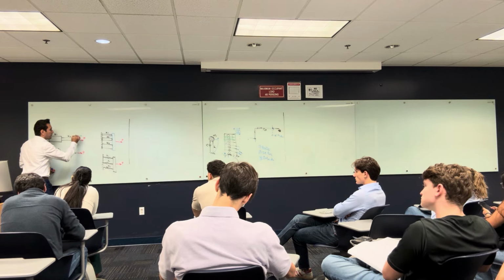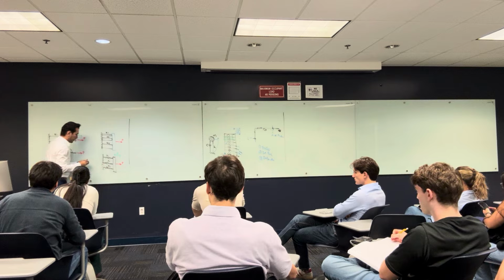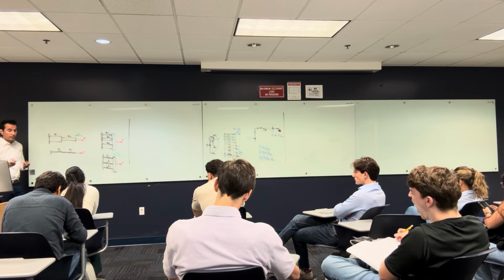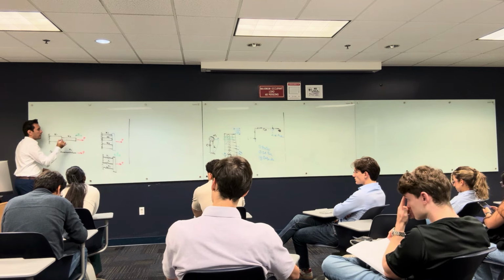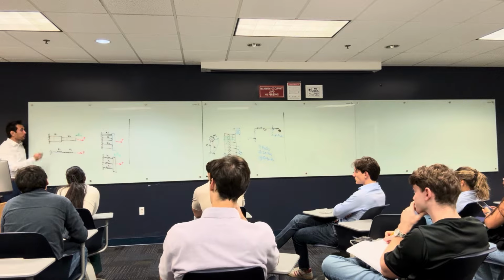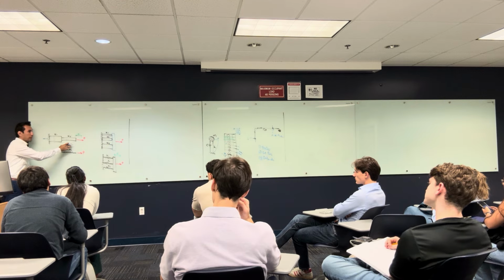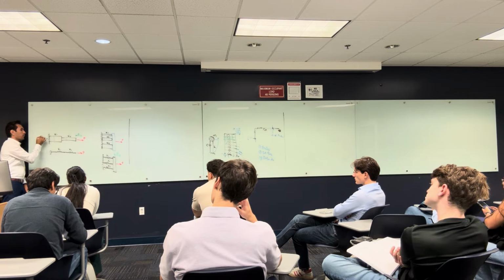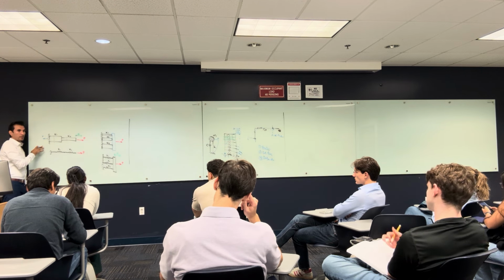All right, I want to find the final deformation that is going to happen after you apply this here. I want to know how much delta we're going to have here and how much delta I'm going to have here. Let's see the difference between the two systems. Let me ask you, what is the internal normal force here? B. And what is the internal normal force here? B. The internal normal force in every one of these sections is B, right? Because if you cut here and you look from the right, it's B. When you look from the left, it's B. That's the reaction. Same thing here. So the normal force is constant here.